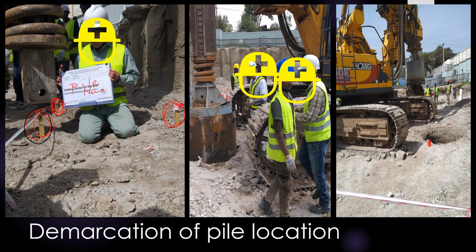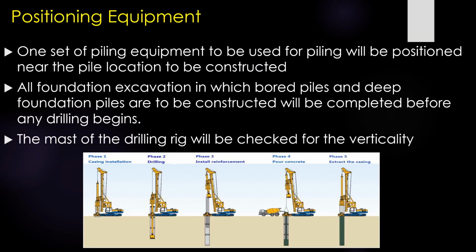Here you can see this is the peg, which is away from the center around how much? 2 meters. This is the center of our pile. Then what we are going to do is, with everything in place, pre-drilling of the borehole can commence, like in the figure here. So pre-drilling may commence here. So this is the starting point.